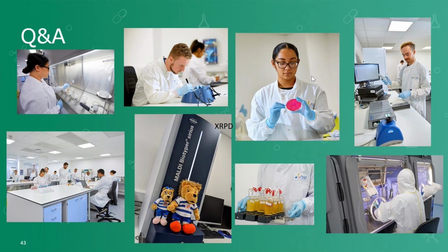The answer to that one is they should always be taken as the production staff would use it. So if the production staff take it with tubing, then take it with tubing. If the production staff don't take it with tubing, then don't. I've been stung in an FDA inspection before when it started off being the same way. Production changed their practices, didn't tell the QC microbiologist, and ended up taking water in slightly different ways, and that related to tubing, non-tubing, and also the flush time as well. So just make sure it's the same.